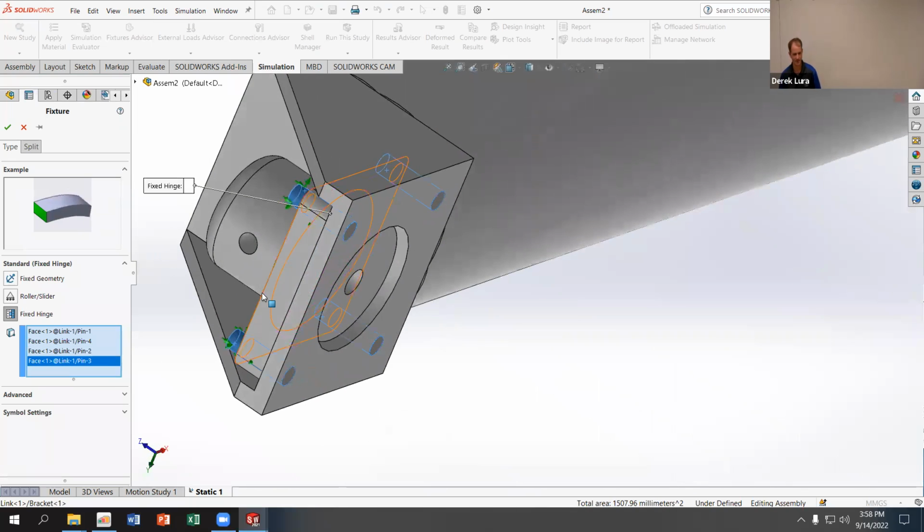Just the sides. If I fix the sides, since there's nothing on the tops and bottoms, it's not going to make any difference. Now you may ask, I could also fix the pin holes inside my arm, but those will give you very different constraints, because I'm going to set up a bonding condition there. This will allow the holes to adjust a little bit around the pin, whereas if I fix just the holes, you have a little bit different dynamics there. So I'm going to accept that.